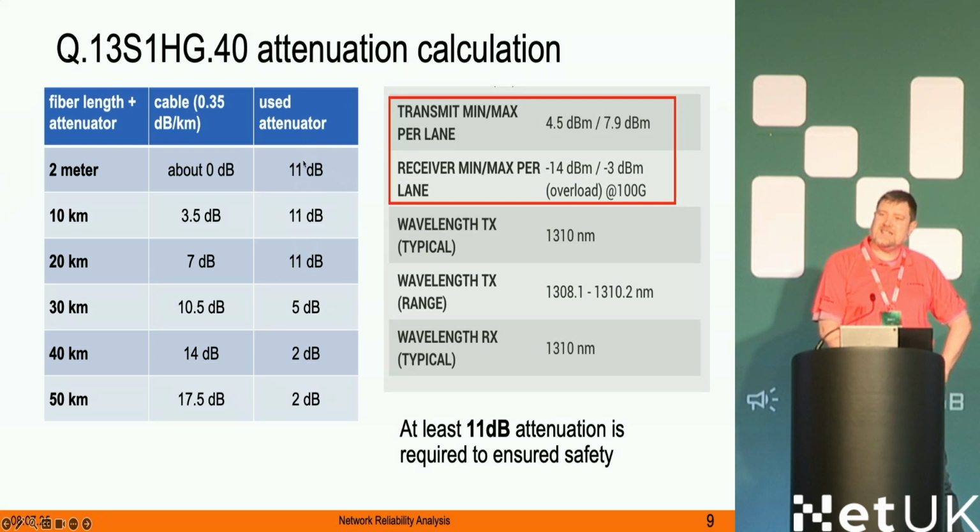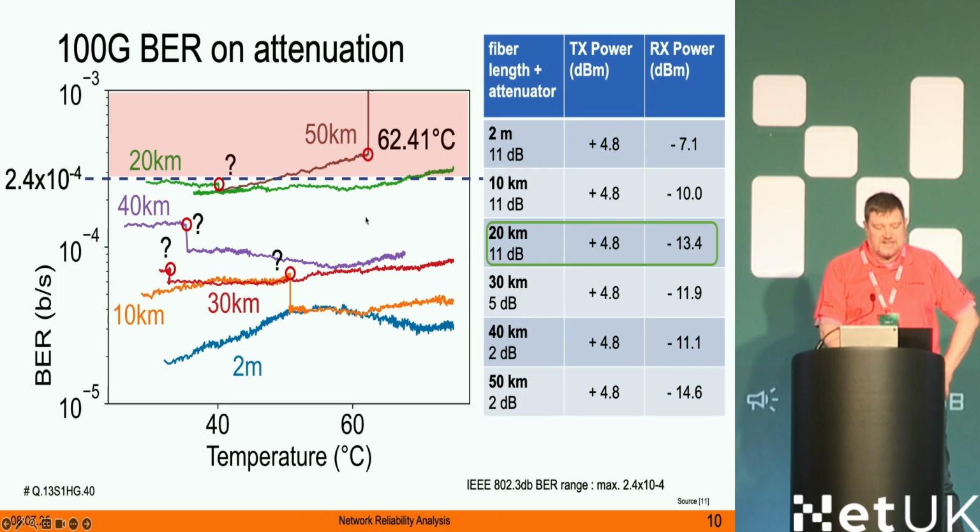So watch out for the ER transceivers, because this is something that can happen, but it also makes it a little bit more difficult to analyze our studies, because I had to attenuate at certain distances. So with 2 meters, I have to attenuate with a strong attenuation of 11 dB, and I kept the first 3 at the same pace and just looked into the diagrams at what bit error rate we get.